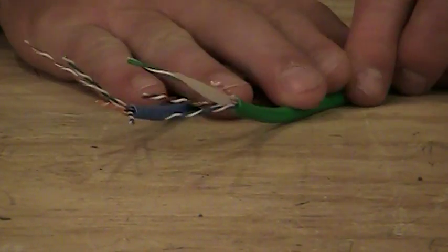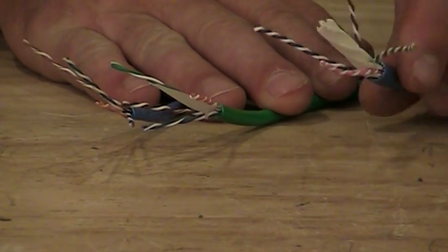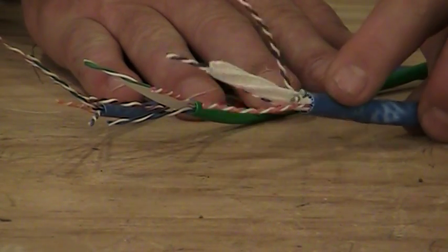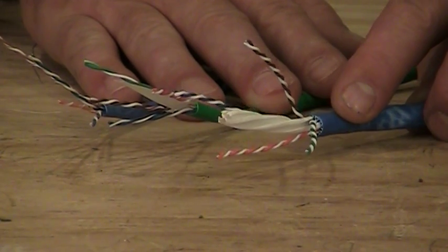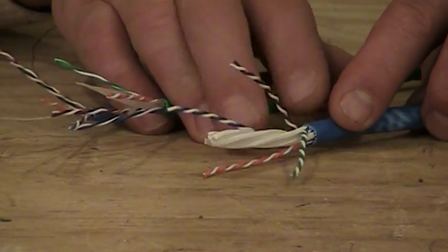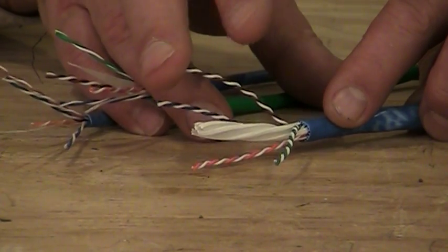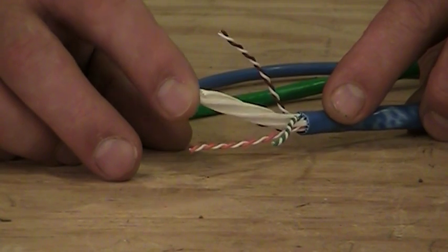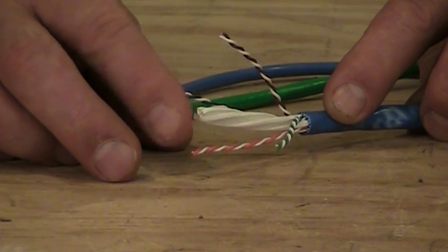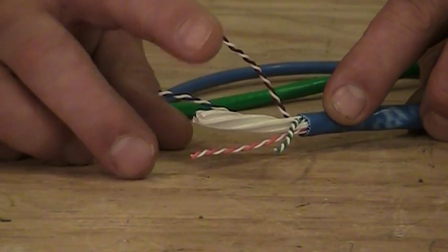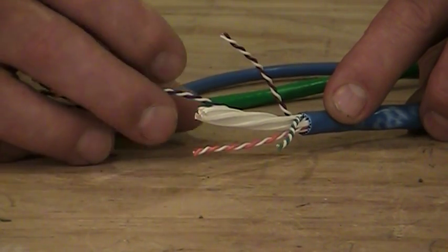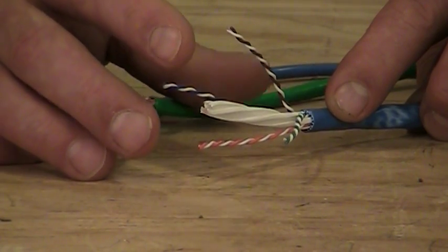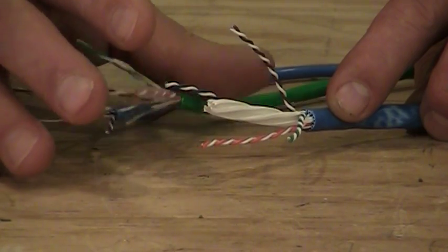Now, the third one is 6A. And 6A is the latest and greatest as far as data networking cable is concerned. You might notice it is significantly thicker than the other 2 cables, and the amount of twisting we're doing in the cabling is getting pretty serious as well. Then we'll also normally find some form of a separator in the cabling here, a little bit bigger than anything you might have seen before, and again, it helps maintain our twistedness between the pairs. We twist the 4 pairs at a certain rate and twist all 4 pairs together at a certain rate to generate a cable that meets 6A standards.